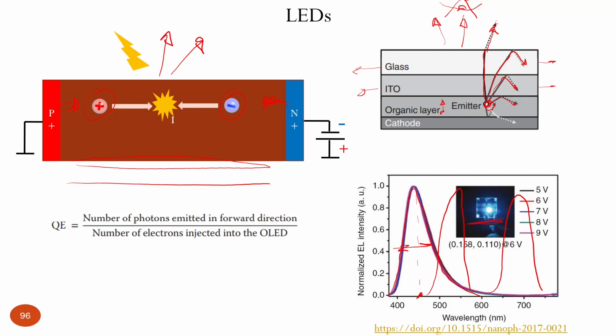You can also use wide bandgap materials which emit in the blue or UV spectrum. Then you will excite some luminophore, which will absorb and re-emit in a broad, wide spectrum. So that's how you can manipulate the spectral distribution of light which we get out from LEDs. But if we have a pristine material, just an active layer of one material, the position of the maximum will be defined by the band gap. So with all these characteristics, we can introduce one of the key parameters for LEDs, which is the quantum efficiency for electroluminescence.